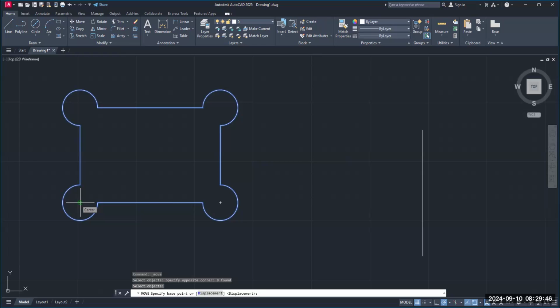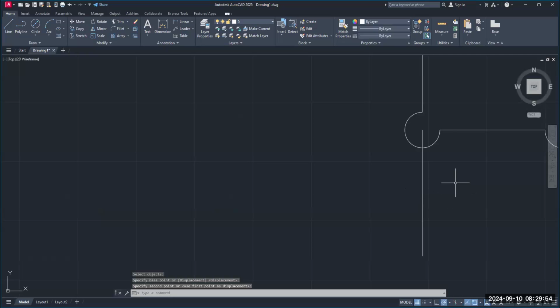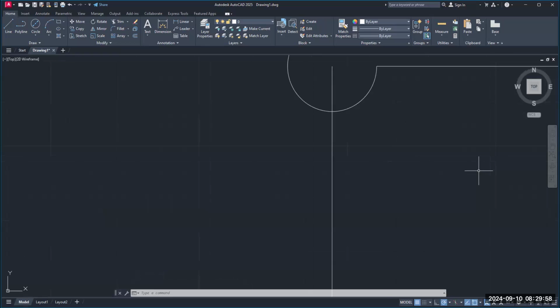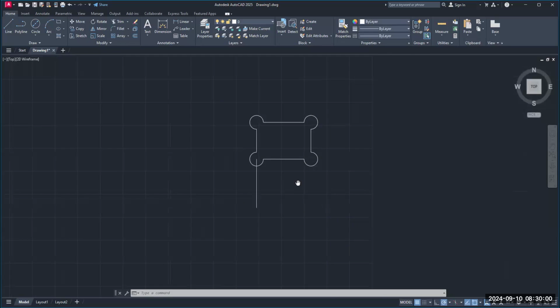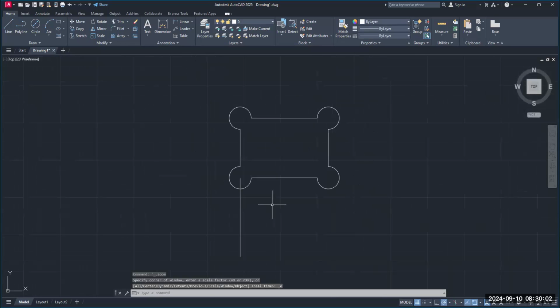Now I can snap to a center point, click, and watch. I'm going to snap right to that endpoint. Click. I can't see all my geometry possibly, so rotate your scroll wheel, pan. You can position it back where you want to. So now I move this object right to that endpoint. Were you successful? Okay, that's good.